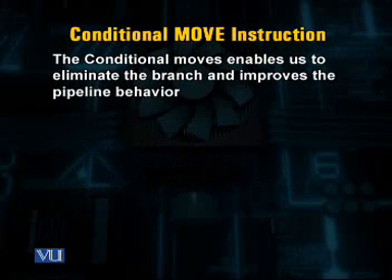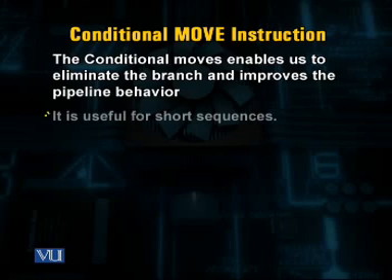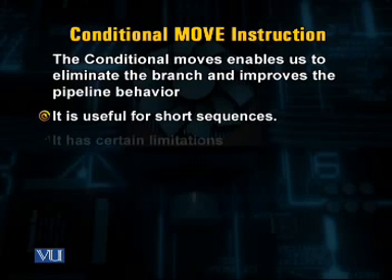The conditional moves, therefore, enable us to eliminate the branch and improve the pipeline behavior, because this basically reduces the condition evaluation process. It is useful for short sequences.